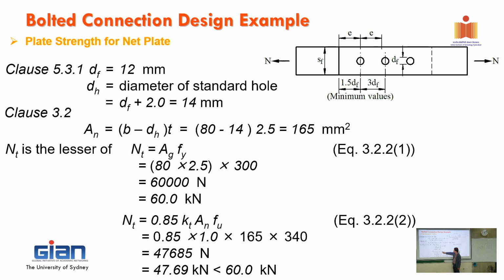So you're using that equation, and with this equation, remember we use Fu, but with this equation we use Fy. Because with a bolt, remember, the stress distribution in the cross section is not as simple as we think. If you have a bolt in here subject to tension, the stress distribution is somehow like this, so we get a lot of stress concentration.